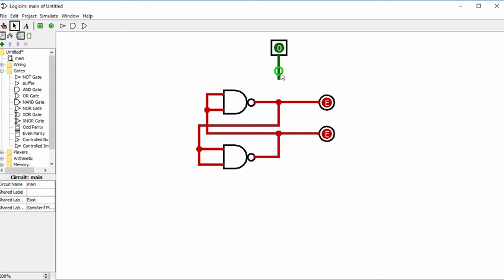What will happen in reality is this circuit will be powered on and it will do something. Here's an example of something it might do. So it might go on to the 1-0 state. Now you can see that it's stable. If I press Control-I now, it's stable. It could be stable in another state. Now I have to force it here in Logisim. So you can see how the 0 and the 1 switch positions. So when it powers up, it can be a 0 or a 1 or a 1 or a 0.